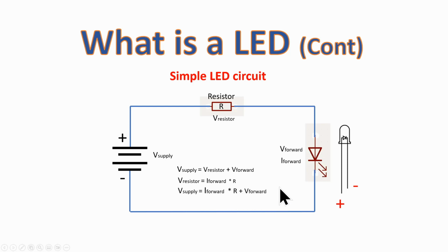And in one of the previous episodes, we talked about how we can add the same thing to both sides of an equation, and we can multiply both sides of the equation by the same amount. So if we apply those two laws and manipulate this formula, we should be able to come out with the resistance that we need: the supply voltage minus the forward voltage of this LED, divided by the desired forward current we want through it.